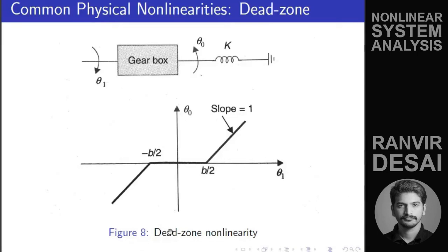But if we want to translate into our DC motor example, you can consider this as the input voltage, and this is the rpm. In input voltage, you can write this as minus 5 volt, plus 5 volt, and this is linear. So the slope will be 4000 divided by 12, so 1000 by 3, about 333 rpm per volt, something of that kind. So that will be the slope of this graph. So this is the dead zone nonlinearity, the fourth type of nonlinearity.